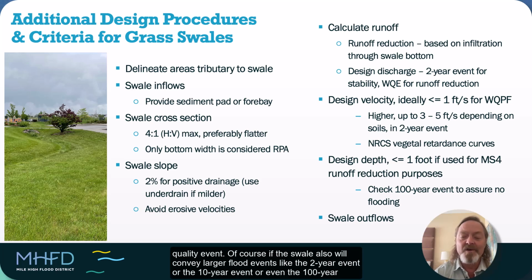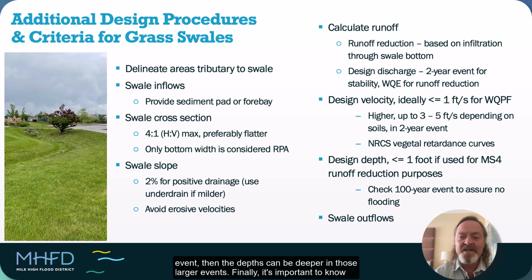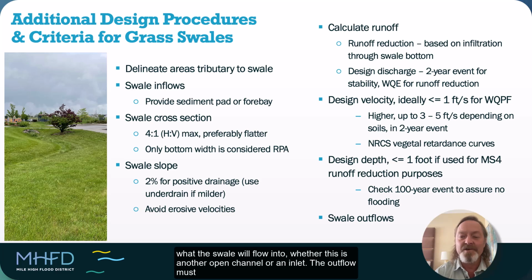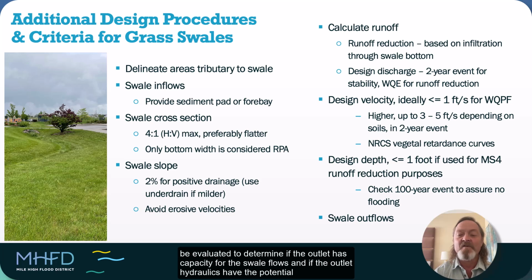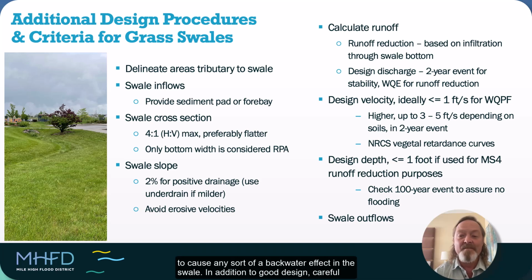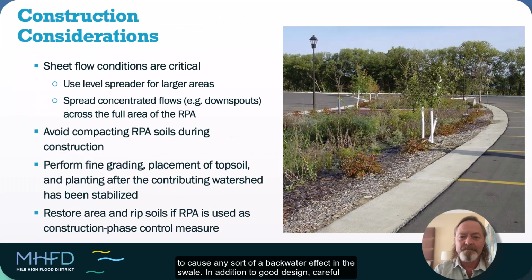Of course, if the swale also will convey larger flood events like the 2-year event or the 10-year event or even the 100-year event, then the depths can be deeper in those larger events. Finally, it's important to know what the swale will flow into, whether this is another open channel or an inlet. The outflow must be evaluated to determine if the outlet has capacity for the swale flows and if the outlet hydraulics have the potential to cause any sort of a backwater effect in the swale.